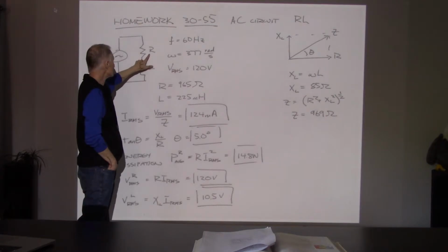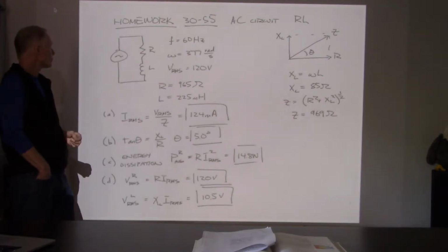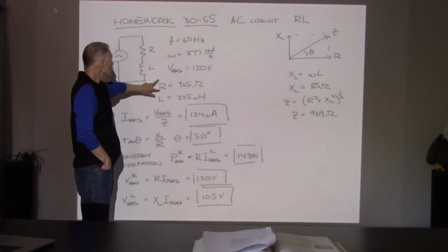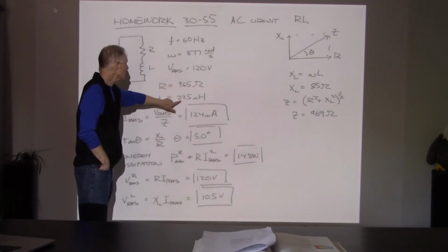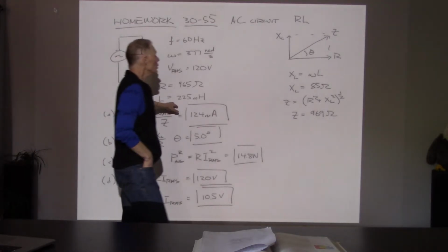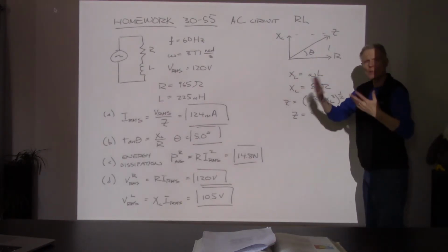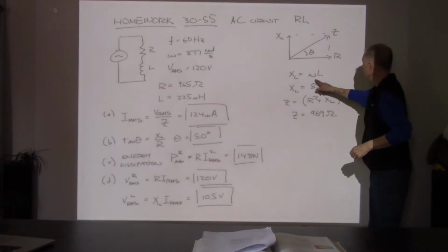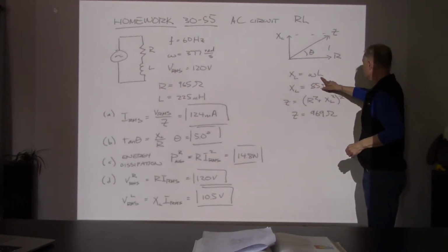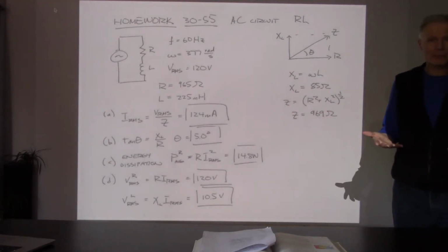And then they tell us the resistance, and they tell us pretty much everything. I'm not sure what's left to calculate in the problem. We will see. This is 965 ohms of resistance, and then 225 millihenries of inductance. Now, oh, I did calculate it. So over here, we got the inductance, but we really want the inductive reactance. So I've got to multiply by omega, and that is going to give us 85 ohms of resistive effect.